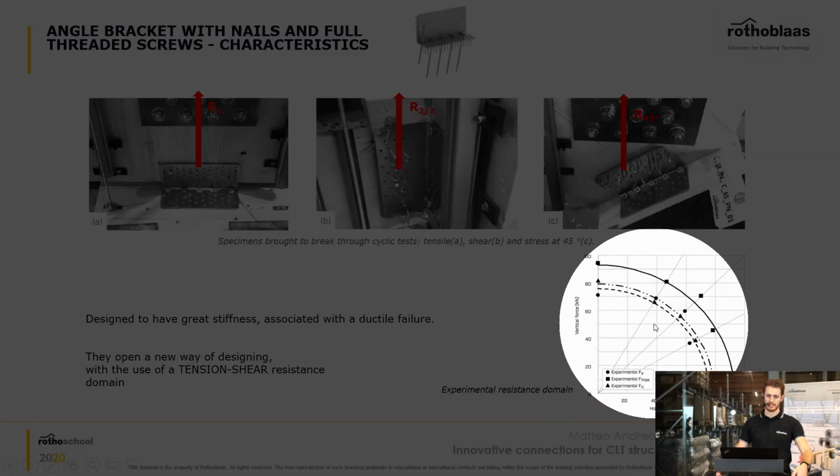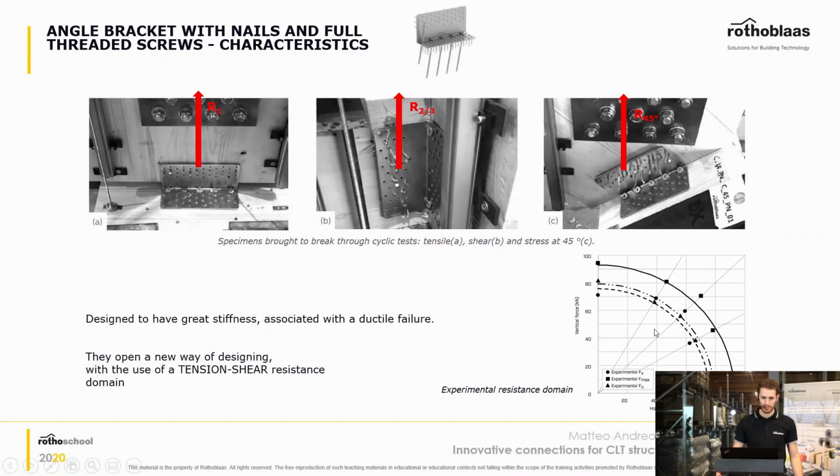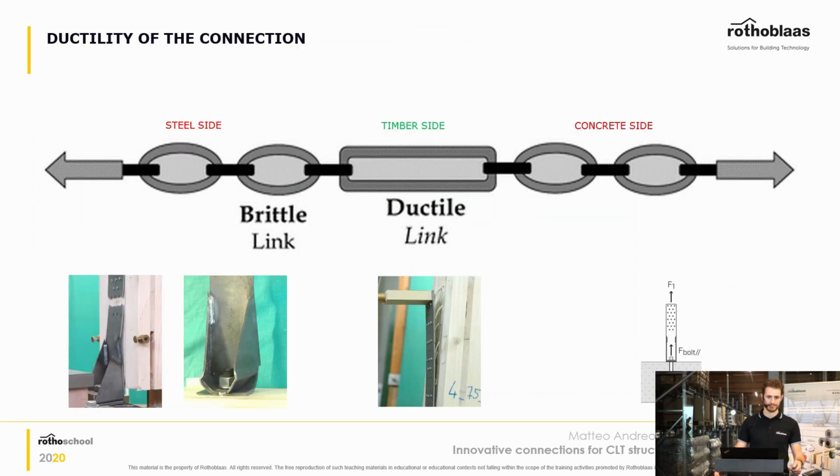And another important thing: since the connection can withstand tension forces and shear forces at the same time, you have a domain of resistance. Of course, if you are inside the domain, your connection is verified. Otherwise, it is not verified.